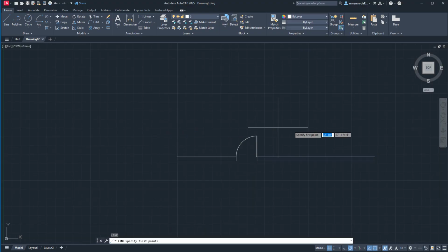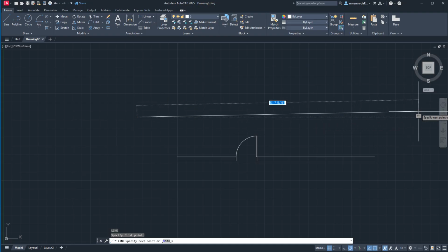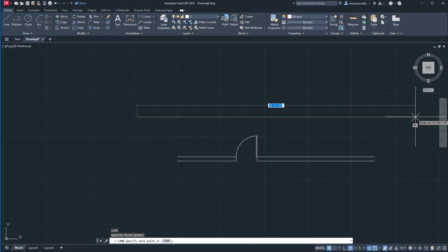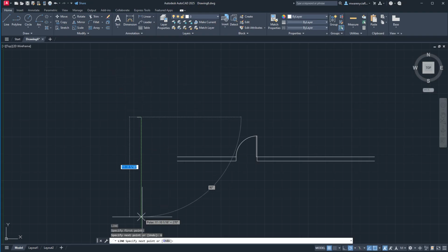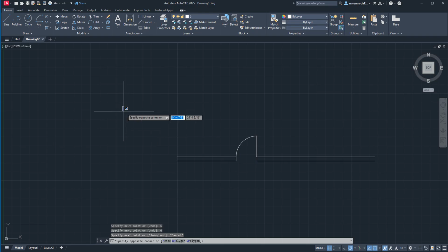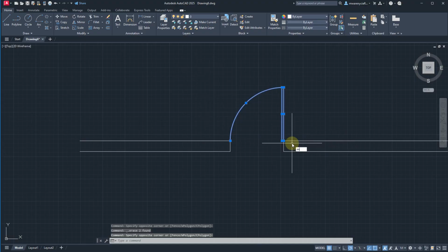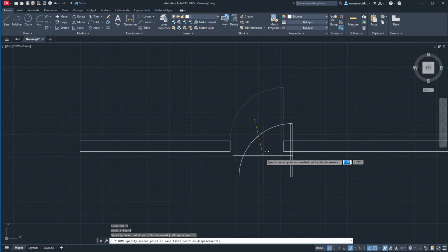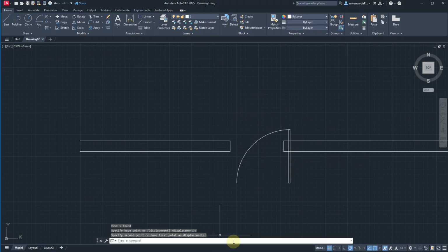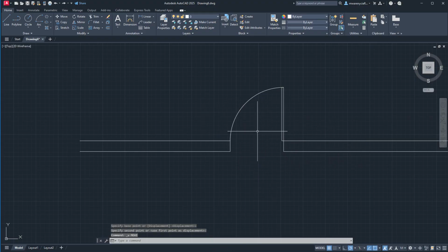In fact, even sometimes when I'm doing lines, if I start a line, I may move the line all the way out here, even if I'm only going 6 inches. And I'll get really big about this when we're working in SketchUp, because SketchUp's even more notorious for kicking you out. Okay, so that's a move, is just select what you want. M, enter, base point, and then second point. And that gets you kind of base however you need to move.